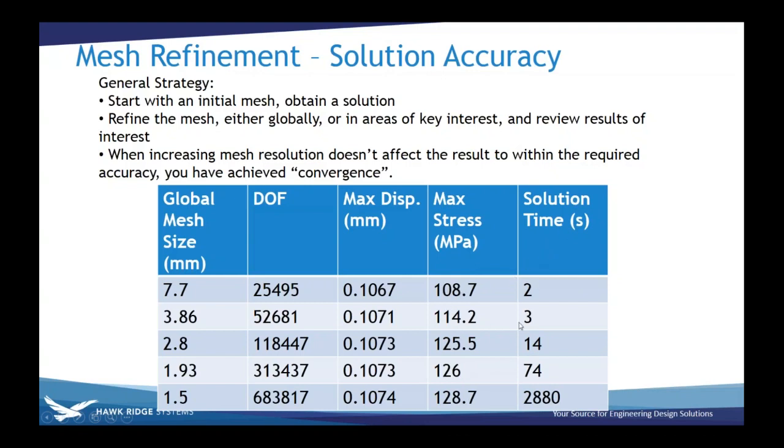And the solution time goes from 2 seconds to, I don't even know what that is in minutes. I did run out of memory in this top one. For the solver I'd selected, there was too much memory for my system. The software wanted to switch me to a different solver that would have been a lot faster, but just for consistency, I stuck with the same solver.